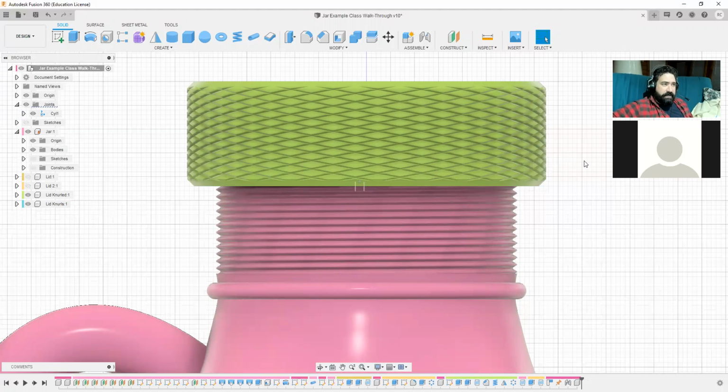Now, this lid, I could then go and add the joint back in, but just for the, oh, there it is. That's weird. When I created the component that first time and I couldn't find it, it was because my history slider was slid back in history a bit, and it was technically before some other things that were reliant on making that component.